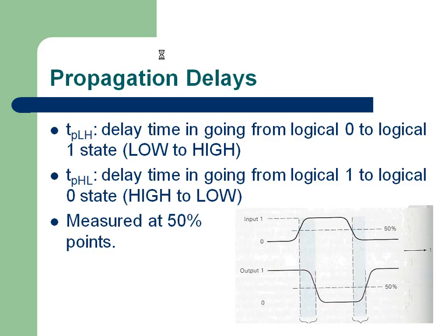This mainly becomes the issue in CMOS. Because in CMOS, it won't require any current practically for the gate to switch. But depending upon the current there, it will take more time to actually switch. Unlike in TTL, DTL and all, there is no absolute minimum current that you need to maintain. Got it? So in CMOS, no problem, you give even 1 nanoampere, the gate will switch, in, let us say, 1 microsecond. Got it? So usually in logic families, when people talk about driving strength, it is also tagged with the delay, the speed. So that's the reason this slide is discussing propagation delay.